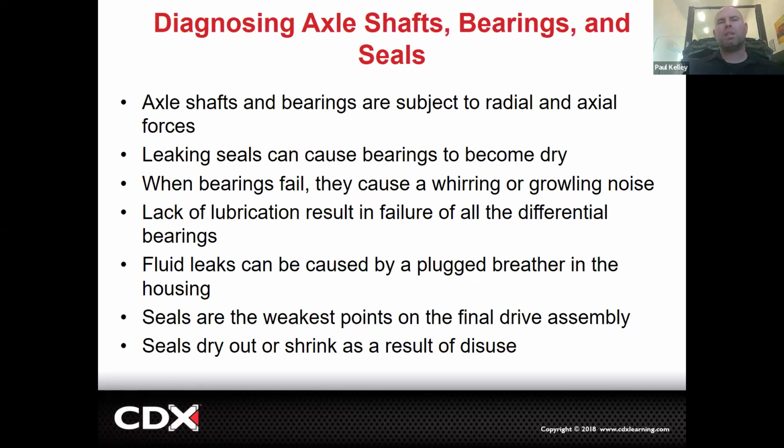But they might change in pitch. If it's pinion bearings, it might sound a bit different. It might be a little more high pitched because the pinion bearings travel faster than, let's say, the differential bearings or the axle bearings, right? If it's a 4-to-1 ratio, the pinion is turning 4 times for every axle turn once. So your pinion bearings may be more like a woo, and your axle bearings may be more like a woo, because they're different frequencies due to different speed.